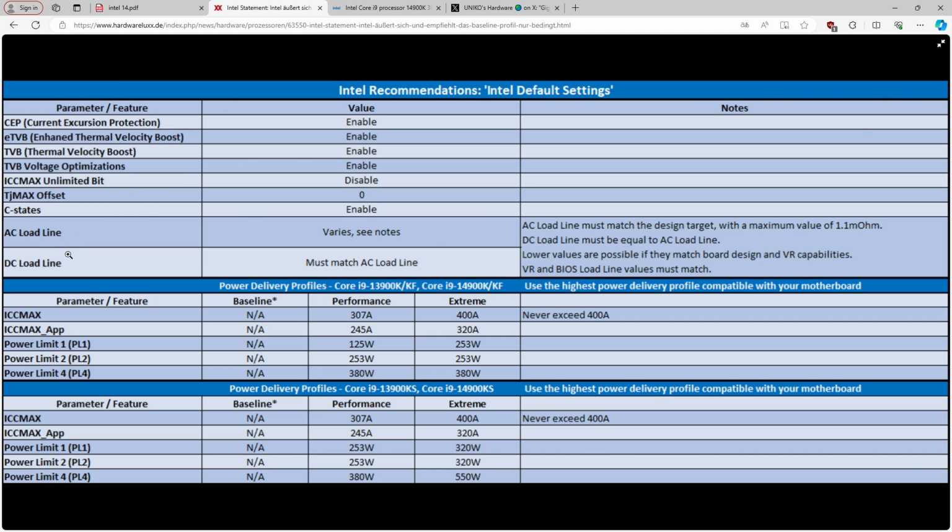And so the thing is, Gigabyte uses 0.4 and 0.9. On some BIOSes in the past, Gigabyte actually used 0.6. Funnily enough, I've been made aware, and I kind of suspected this but didn't really bother to investigate, that Gigabyte's been basically changing the AC load line value up and down with BIOS updates, and mostly down. I guess they've been progressively lowering it more and more as they were like, well, if we lower it another 0.1, it'll give us higher benchmark scores, which is not great.